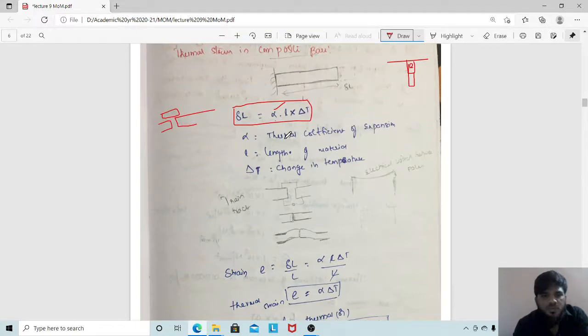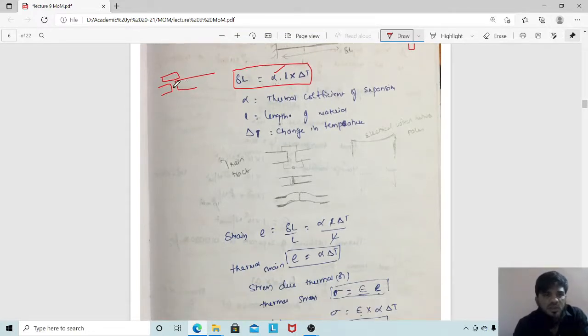So if this small gap is not provided in the railway track, what happens generally is, when summer comes, the track will try to expand. If this gap is not provided, the rails will try to merge like this and create a bulge. They will try to move one above the other. When the train passes through and they are bulged out, derailing of the train may happen. Because of that, we give some provision for it to expand.